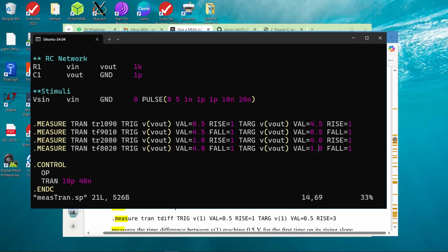So how many of you are done with all the 4 rise fall and all the 2 rise delay and fall delays? Okay, good. So you can now start finding out the pulse width and the period of the output wave. Period. And you calculate that by taking the output 50% to 50%, pulse width from 50% to 50%. Okay.